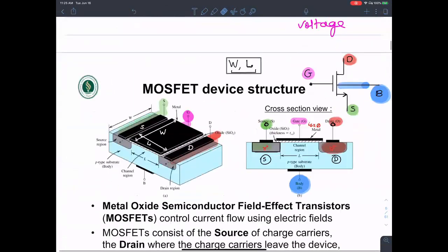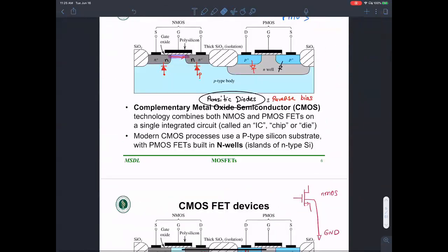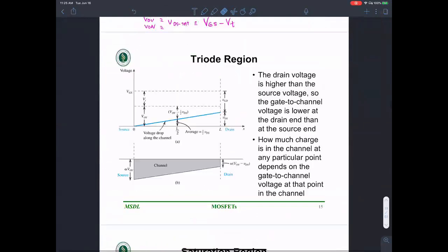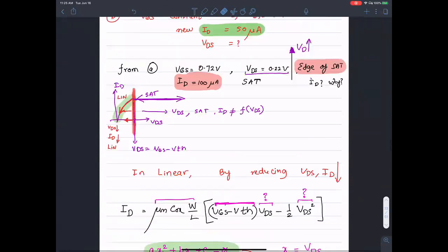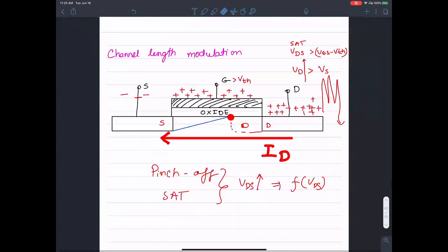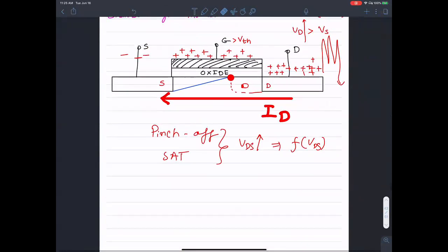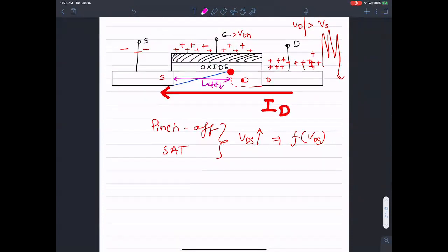So please bear with me as I go all the way back down. Here, as a result of channel length modulation, the effective channel length, that is between the drain and source, and I'm going to show this using this color, that is the L effective, has decreased.